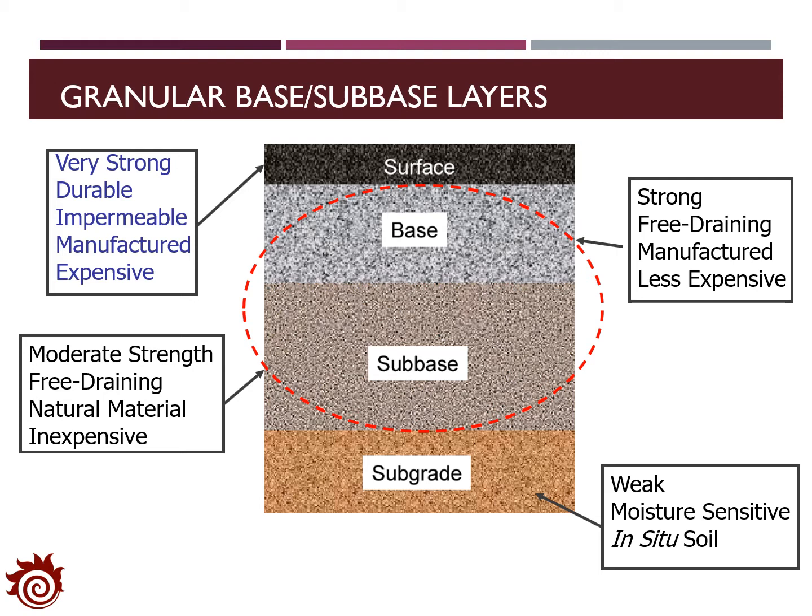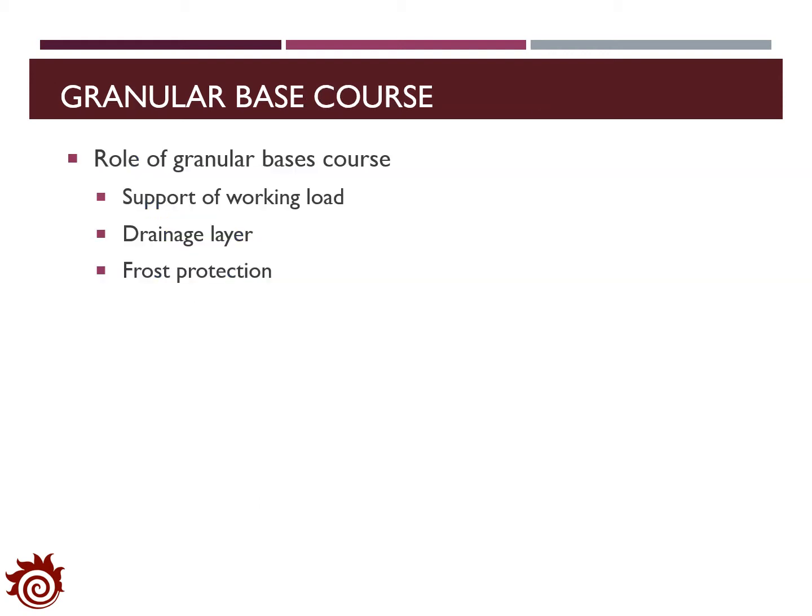About the subgrade layer, there are base and subbase layers. Both of them have free draining capability. Usually, the strength of the base layer is much larger than the subbase layer. Both base and subbase layers are constructed to support the load applied to the asphalt surface. In this lecture, we will focus on introducing the property of base and subbase layers and the materials applied for them. Both base and subbase layers are actually granular-based courses.